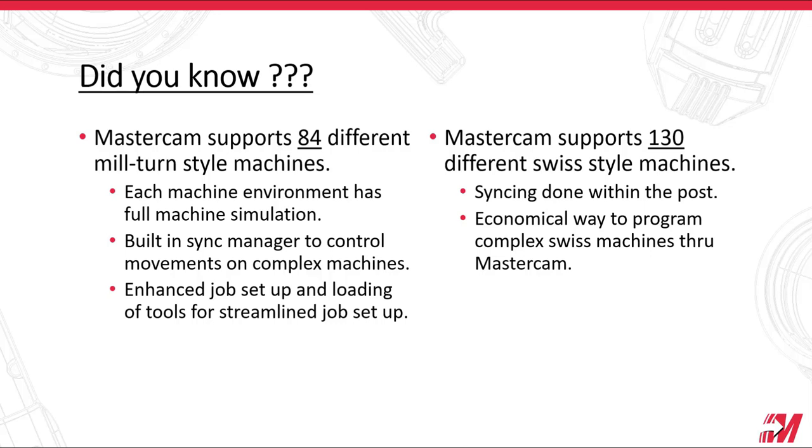Mastercam also supports 130 different Swiss style machines. You're not going to be running Swiss in the MillTurn product. It's going to be done in our Lathe product. The syncing is done within the post, so in the miscellaneous values is where we sync positions. This is a very economical way to program complex Swiss machines through Mastercam. One note, you're not going to get full machine simulation, but most Swiss users can prove the code out on the machine pretty easily. So if you guys are looking for some Swiss machines or MillTurn machines, definitely let us know.